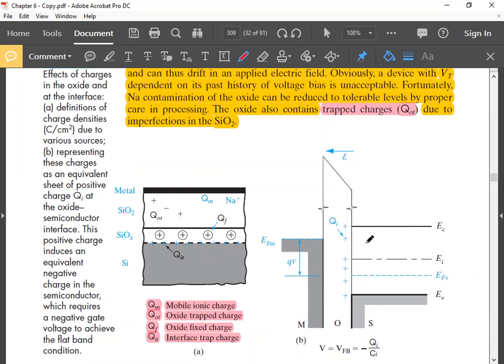In that closed chamber, the bare silicon is placed and oxygen is supplied. The temperature is raised. There may be some catalysts also to assist the reaction between oxygen and silicon. So the oxygen reacts with the silicon at the surface and forms the silicon dioxide layer.